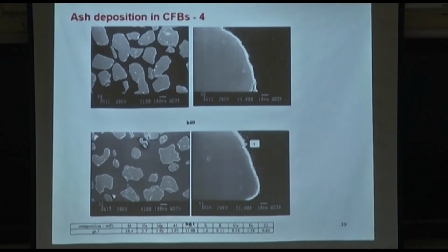And after 28 or 30 hours, it had captured so many particles into the agglomerate that the fluidization velocity that we are maintaining, about 3.5 meters per second circulating, was not able to break those agglomerates up anymore. So what happened? The bed actually slumped.